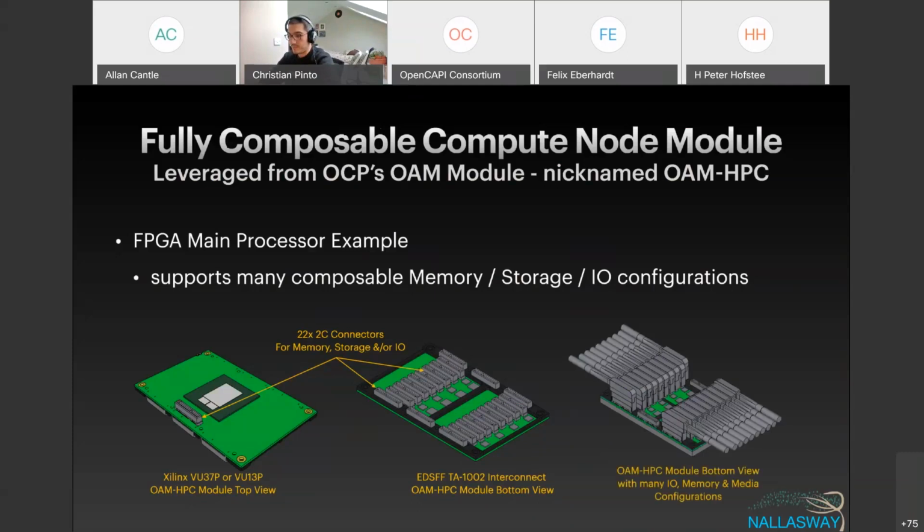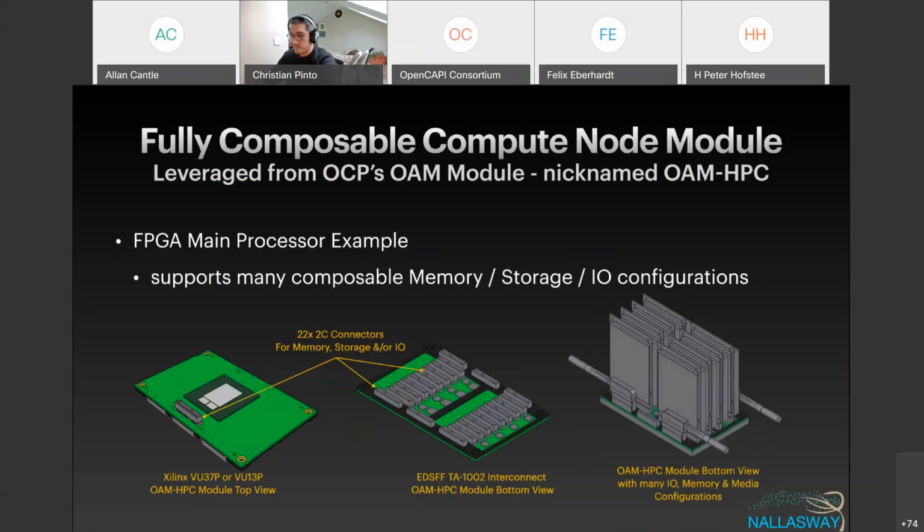And so if we look, we can see that with an FPGA, we could have cabled IO, OMI differential DIMMs connected, the E1.S module connected, E3.S, or the OCP NIC 3.0, all connected into the same module, giving you true composability. And just for good measure, I've shown a mix of all of the technologies in one module. And obviously an FPGA with its configurable firmware can give us complete access to these different configurations. And so we've got this true Lego block composability in a very dense module here, which is quite attractive.